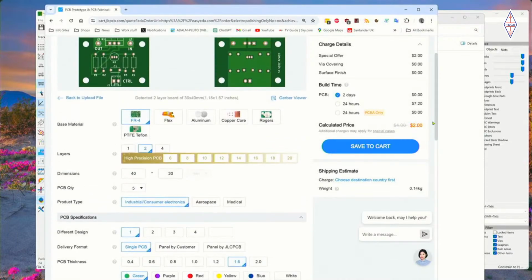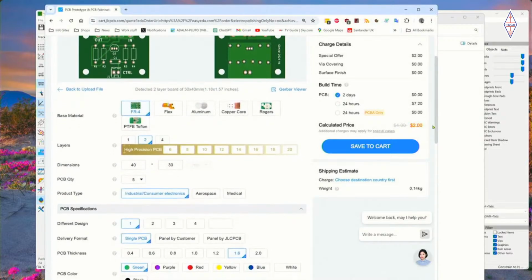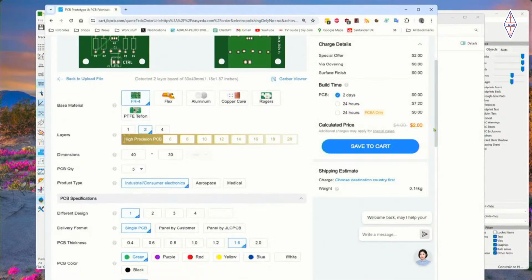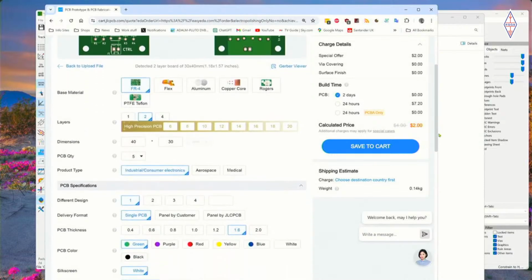Yes. And then one other thing, I don't think we mentioned the word, and again, I'm trying to help people who may see words and think, well, what does that mean? There's a word that's commonly used in industry called resist. And that's that sort of green in many cases, and on this design, that's that layer of effectively a paint or whatever it is on the top and the bottom, which just provides insulation and protects those copper tracks from being just exposed. And that's called resist. So if you see that on a circuit board design or anything, or what color resist, that's because that's what that is called. That layer of extra insulation material just to cover up the copper. I hope you don't mind me mentioning that, Mike.